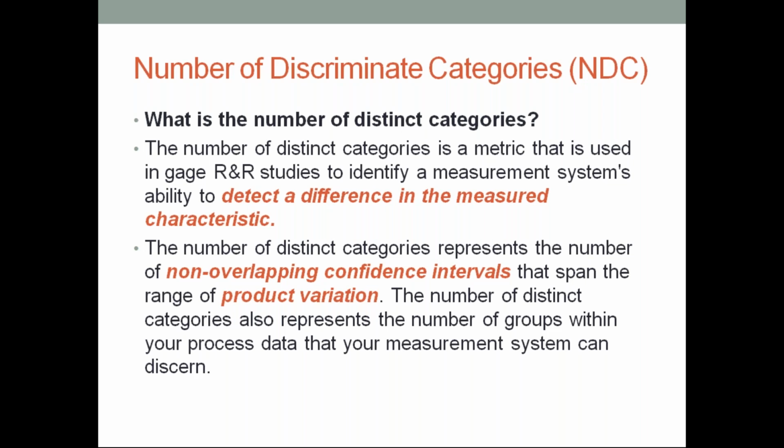If you have 3, for example, or 4, then you probably have statistically the amount of confidence in that data as using a gas gauge in your car, which is not very impressive. In fact, if you're doing SPC, you should have an NDC of 10 at a minimum, and the requirement of having an NDC of 5 is woefully inadequate for SPC.